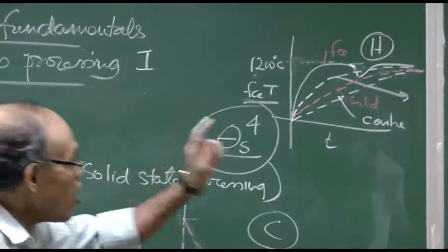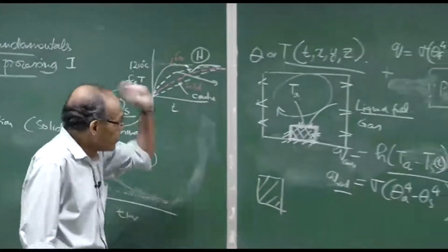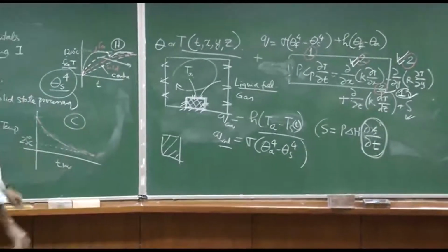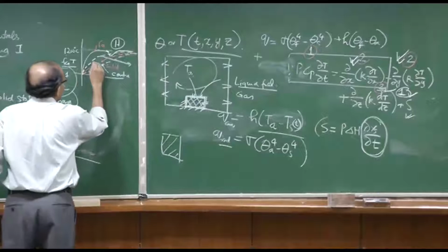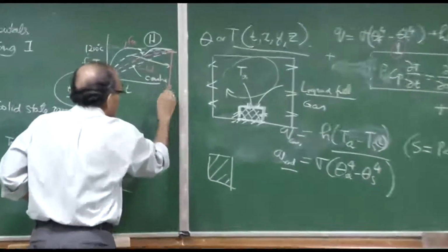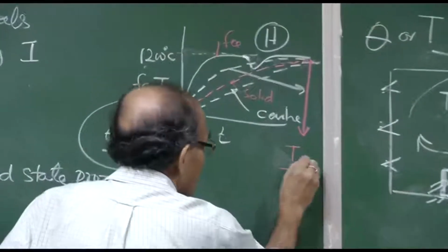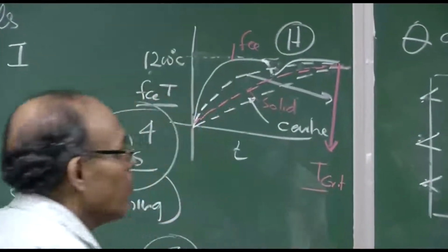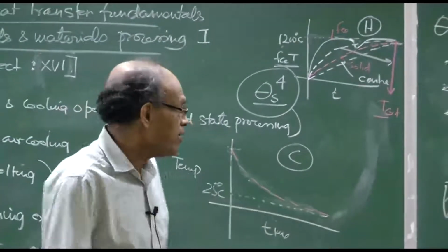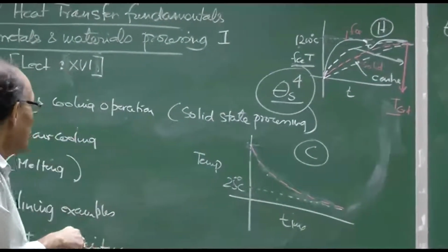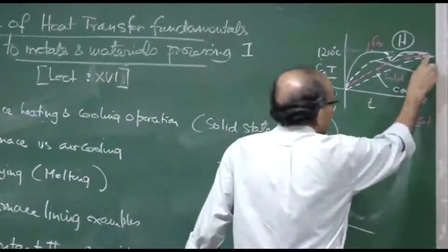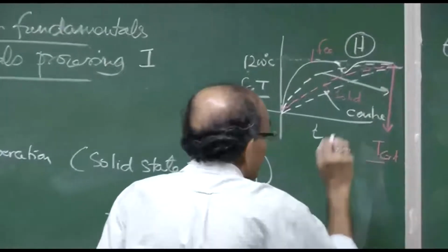So, once we write down the equation, write down the boundary conditions, and solve the equations through a numerical procedure, we should be able to generate these curves, and therefore, we will be able to find out at what critical time there is a thermal equilibrium between the ingot and the furnace, and that tells us that the ingot has reached a homogenization temperature at this particular point itself.